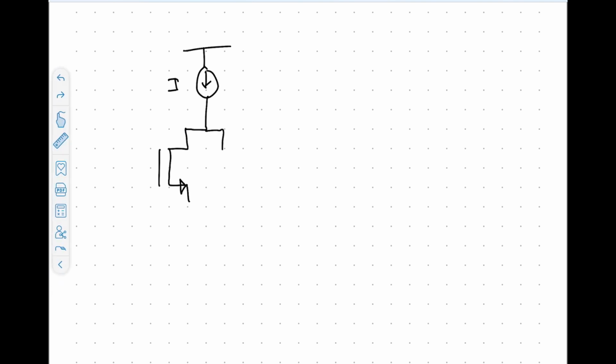So to get right into it, the core of the structure is a current mirror on the top, which then branches off to two FETs, like this. And then there's a current mirror on the bottom. And then, before we get into that, I'd like to show you how this actually gets biased.